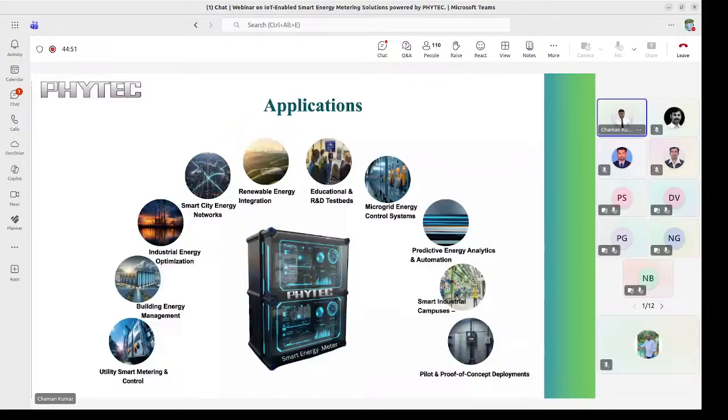And SPI and I2C for industries. It has CAN, and Modbus RS485 is also available. An optical UART is also available. For the security layer, we have the TPM, and tamper detection is also there. Secure boot is also available. So mostly whatever we need for a DCU, we have all implemented here. And for industrial grade input output, it has 24 volt input output available. An SPI LCD interface is also available. Okay, so these are all the features of this data concentrator unit that will be provided by us.